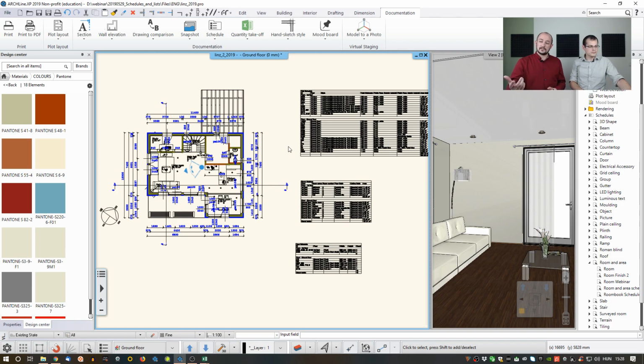If you, for any reason, do not need this bidirectional connection, but you need those a little bit more detailed Excel files with all the formulas inside and all sorts of details that you just saw in this room and area Excel file I created before, then you will use the quantity takeoff tool. Those are kind of similar, a little bit overlapping each other, but for two different purposes. Yes. One is for scheduling and making changes bidirectional. One is explicitly for just making calculations and extracting information in a way that you cannot do otherwise.